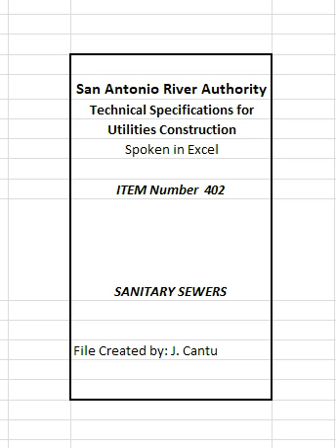A go/no-go deflection testing mandrel or gauge shall be furnished at the contractor's expense and shall be used in testing pipe deflection for acceptance, unless directed otherwise by the engineer. The deflection testing gauge used shall be the fixed size or multi-size type as manufactured by Herco Enterprises, Inc., or engineer approved equal. Tests shall be performed no earlier than 30 days after installation and compaction have been completed. The tests shall be performed without mechanical pulling devices.